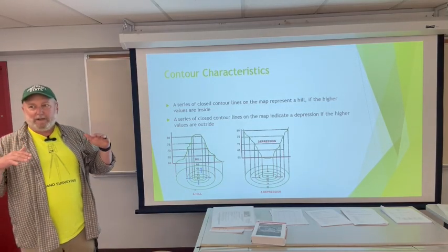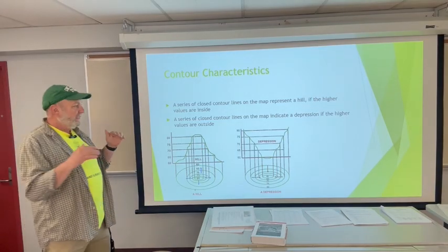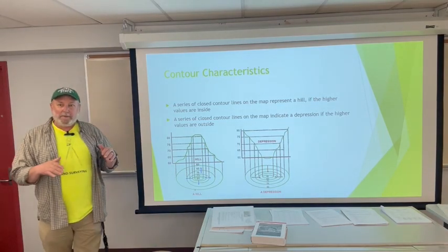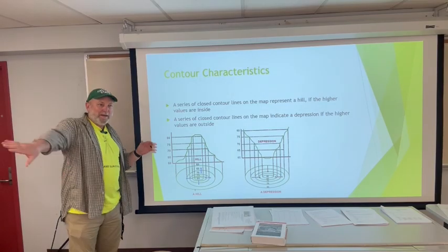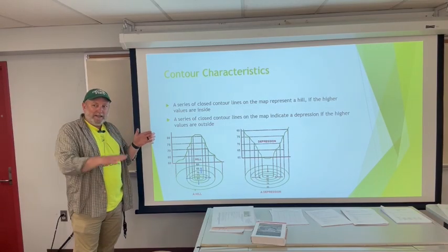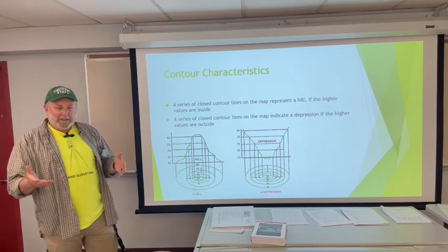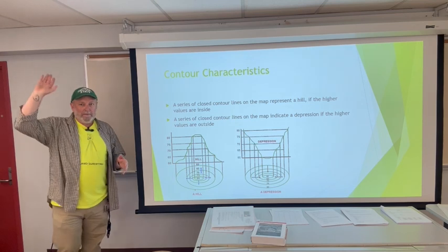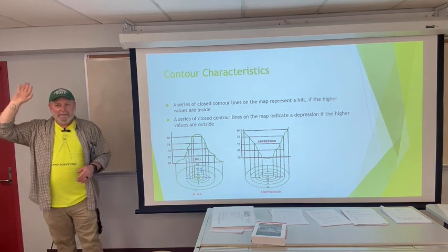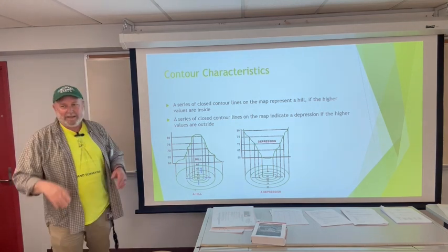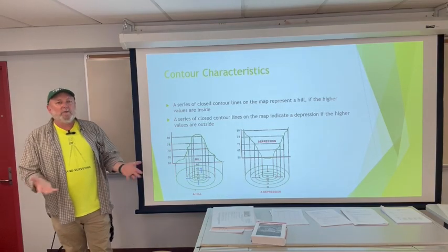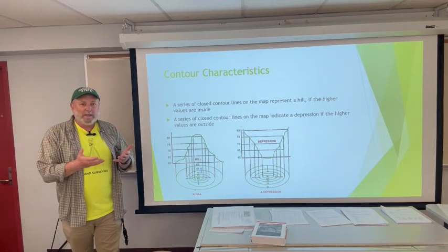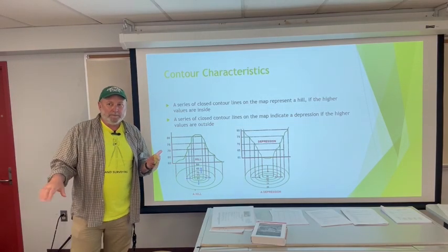It's always retaining water. A detention basin, think of back when you were a kid in grade school. You got in trouble, you got detention. Everybody was released, you were held back and then released later. So detention basins, am I the only one that had detention as a kid? Probably. That's fine. Detention basins will collect water during a storm, hold it, and release it out slowly.